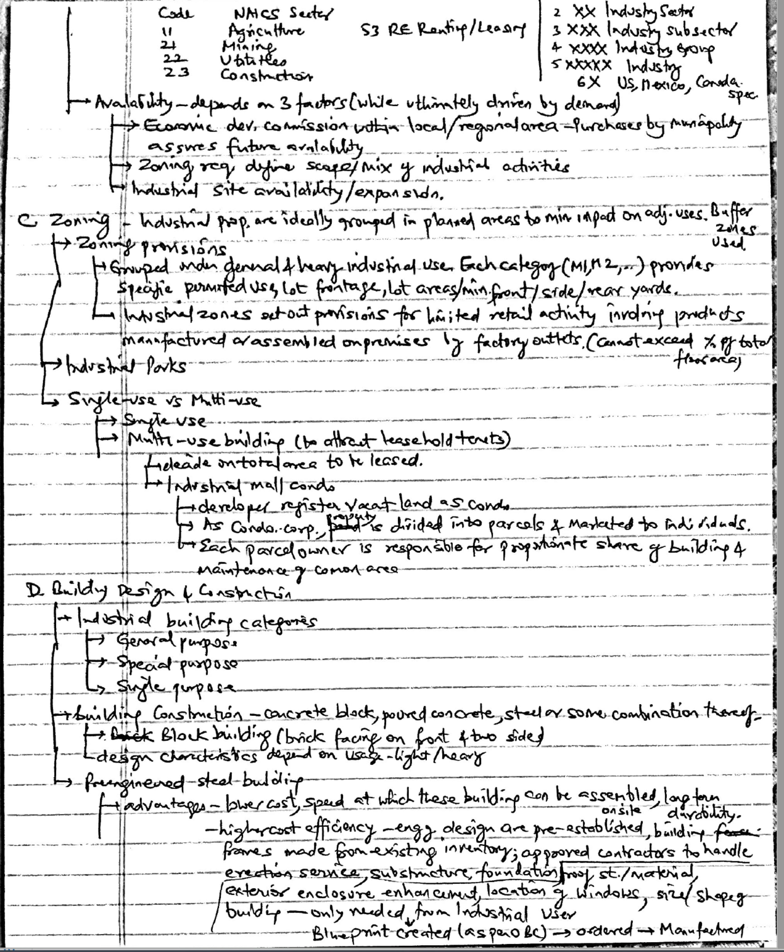Most build design activities begin with a detailed analysis of the user needs, building site criteria, and a detailed costing. Commercial brokers typically have extensive information concerning hard and soft costs and range of typical land use to help in cost estimating. Hard costs include structure, mechanical components, site preparation, contractor overhead and profit. Soft costs include project management, engineering, legal and consulting fees, financing charges, and connection fees.